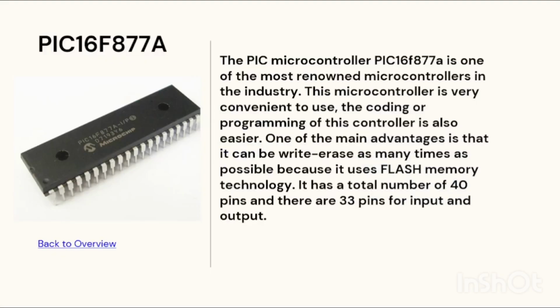PIC 16F877A. The PIC microcontroller PIC 16F877A is one of the most renowned microcontrollers in the industry. This microcontroller is very convenient to use. The coding or programming of this controller is also easier. One of the main advantages is that it can be read and erased as many times as possible because it uses flash memory technology. It has a total of 40 pins and there are 33 pins for input and output.